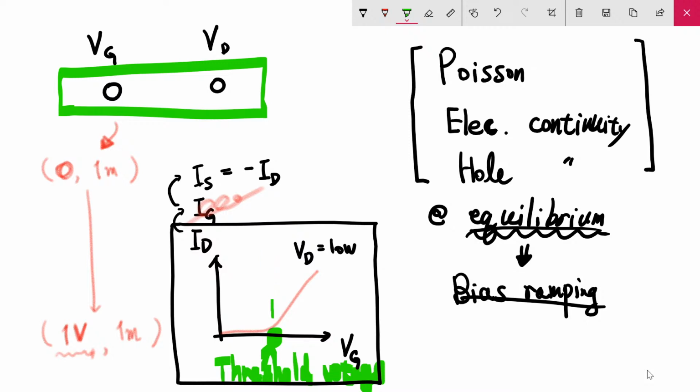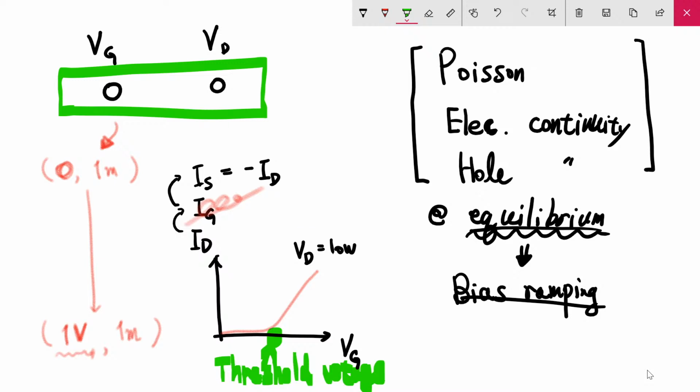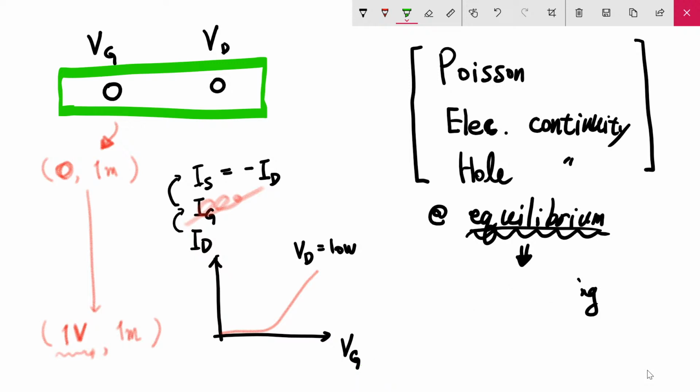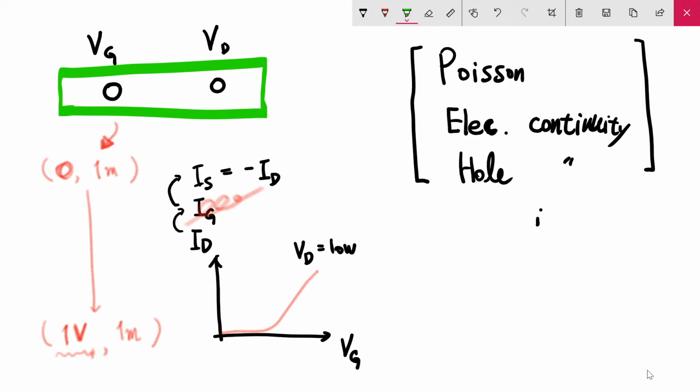Of course, this curve is obtained in linear scale. Your x-axis and y-axis are in linear scale, but in this case you have to draw other important graphs. Use the same data, but draw VG and ID, with ID in log 10 scale.